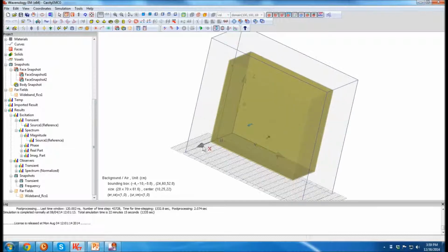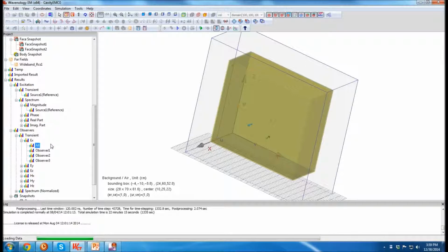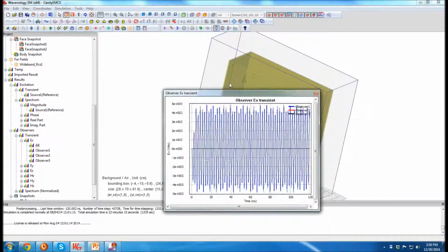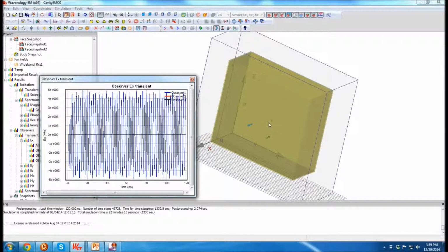So after that, let's check out the transient behavior. You give that shape like BHW shape, and now we want to observe the EX, EY, EZ. If we check all the results, you can see there's only one signal surviving. That is the first observer, which is inside this PC box. The other two are all 0. This makes sense because the metal shielded everything, and nothing comes out.